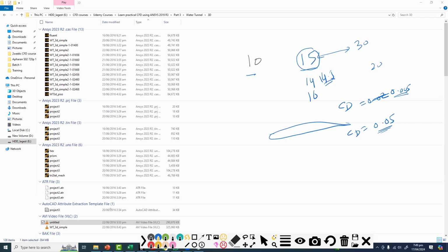So when you set up the case, maybe you made the geometry the wrong way. Maybe the chord length is different. Maybe the aerofoil is different. Maybe the domain you made is not the correct one. Maybe your meshing is not correct. Maybe you have not set the proper settings in the CFD software. Maybe your reference values are wrong.